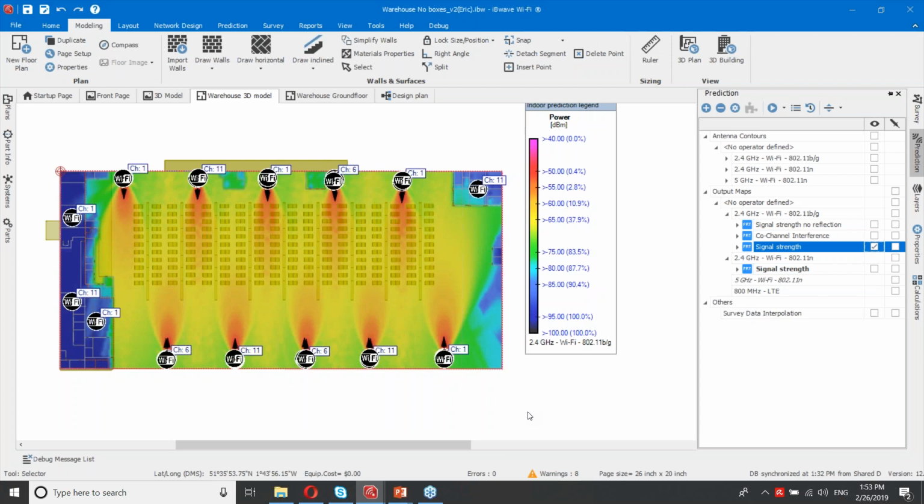And so you would want to have your power for 5 gigahertz at least 6 dB higher, if not more. Now, why not more? Maybe it needs more because antenna characteristics are not the same at 2.4 and 5. I have shown you the radiation patterns at 2.4 and 5. They are similar, but they are not the same, and your gains may be a little bit different. That's why in this case, I have decided to go even higher with power.